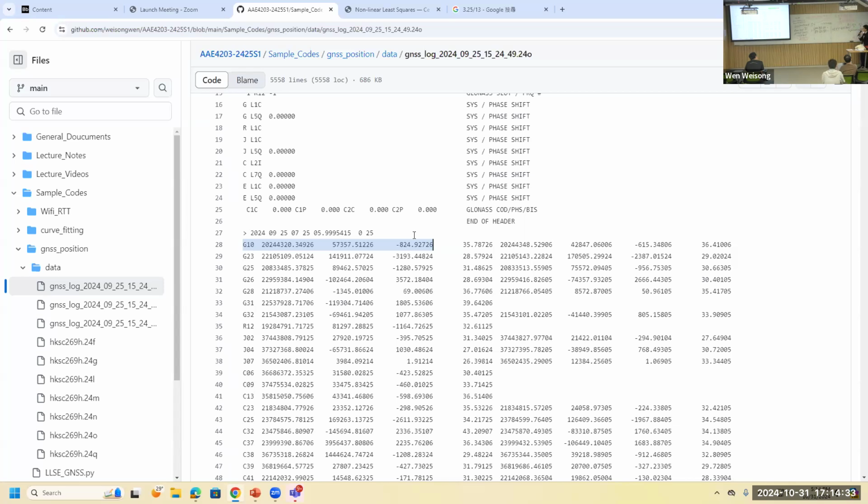So because of the motion differences, for example, the direction is different and the magnitude of the velocity is different, we have the Doppler measurements. This one corresponds to this row. You see, this one is quite small, right? So this is the case where the difference of the motion is quite small. In this case, we get this measurement model, the so-called Doppler measurement model.